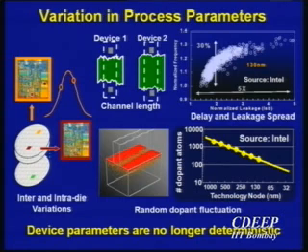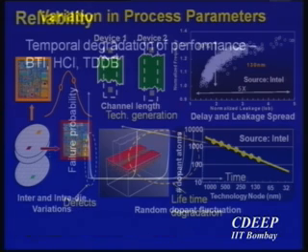So even though you might be designing your microprocessors to work at 5 gigahertz, let's say, you're going to get some which operate at 4 gigahertz, but you're also going to get some which operate at 6 gigahertz. And now we can make some money by selling those 6 gigahertz chips at a higher price, right? People do that, and it's called speed binning. But the interesting thing is, what can we really do under these variations? How do I design with these unreliable components? That turned out to be important.